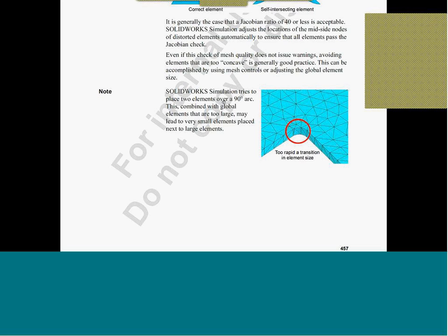Second, as soon as assembly comes into the picture, and that too realistic assemblies, there are high chances of having singularity, and the software might end up refining the mesh at singularity locations instead of refining at the right location, and that can confuse the software. Hence, I suggest it may not be a great idea to use adaptive techniques in assembly.